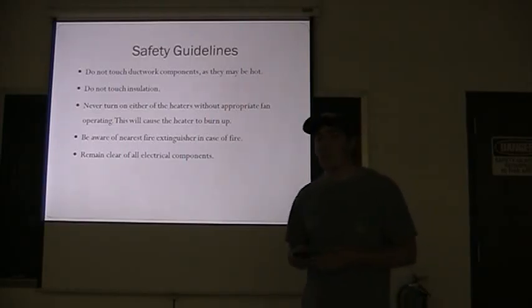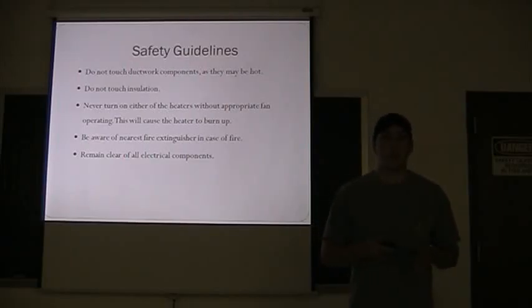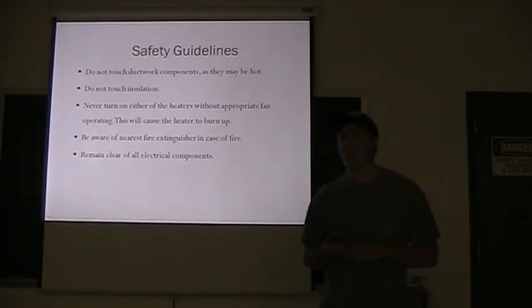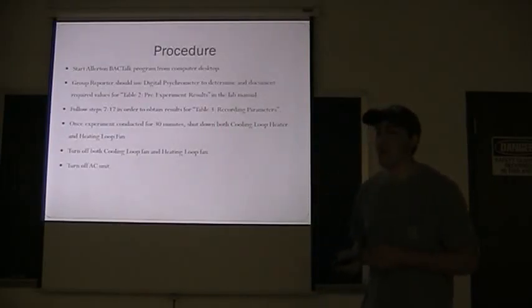Some safety guidelines for the experiment: don't touch the ductwork because it's going to be hot. Don't touch the insulation. Never turn on either of the heaters without the appropriate fans operating, because that's going to cause the heater to burn up. And then be aware of the nearest fire extinguisher in case a fire were to happen, and just remain clear of all the electrical components.